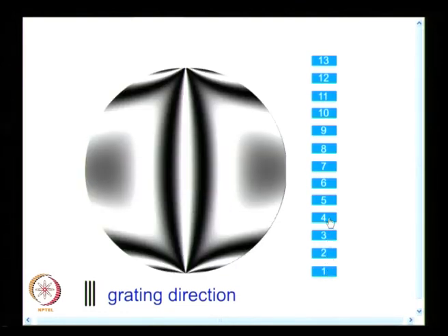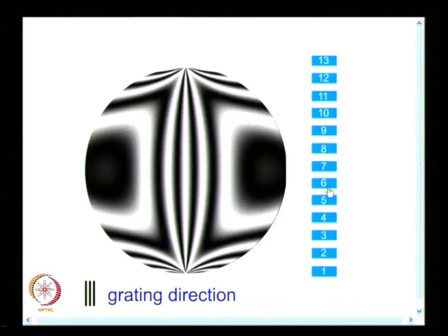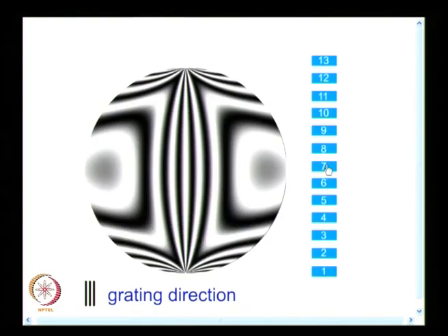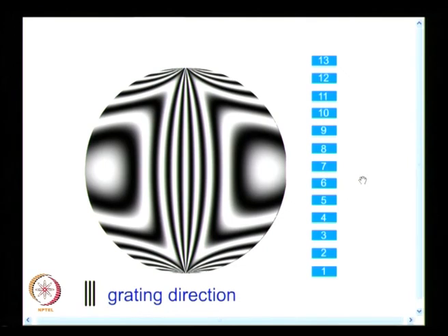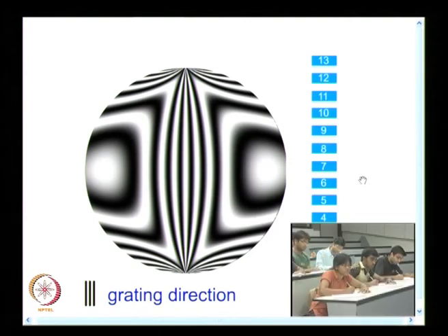I see more and more fringes appear, and probably this sketch you can make because you do not have many fringes, but it gives you the geometric shape of the fringes reasonably well, because at a later point when you have occasion to see the experimental result, you could easily say I have seen these patterns earlier and they would be for a disk, it is only u displacement.